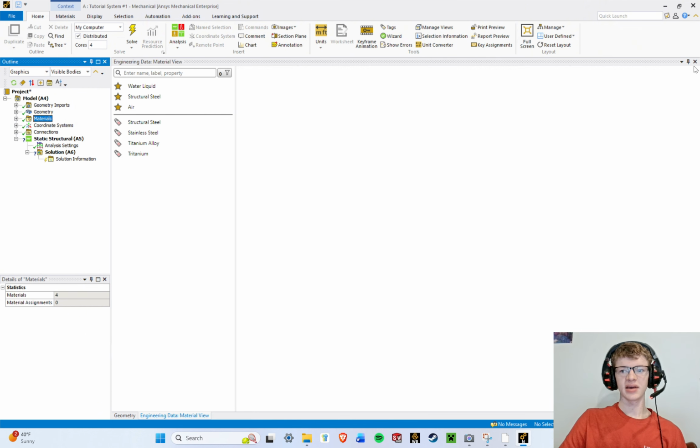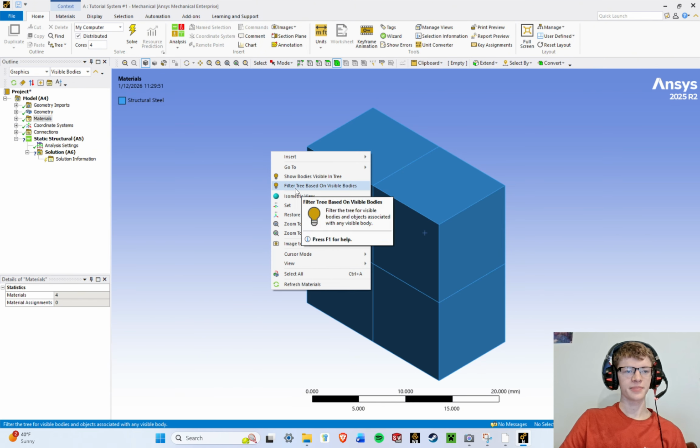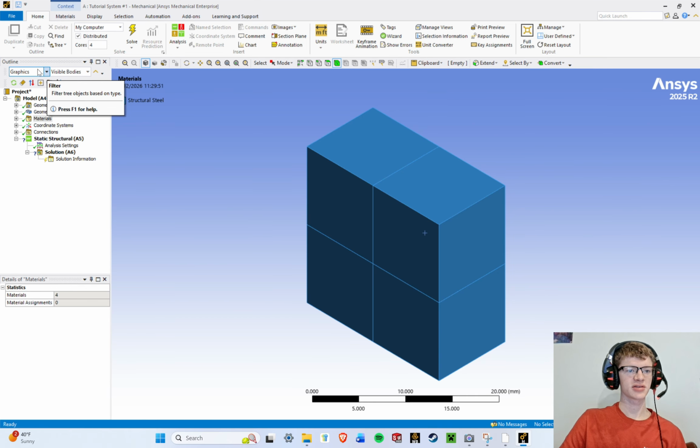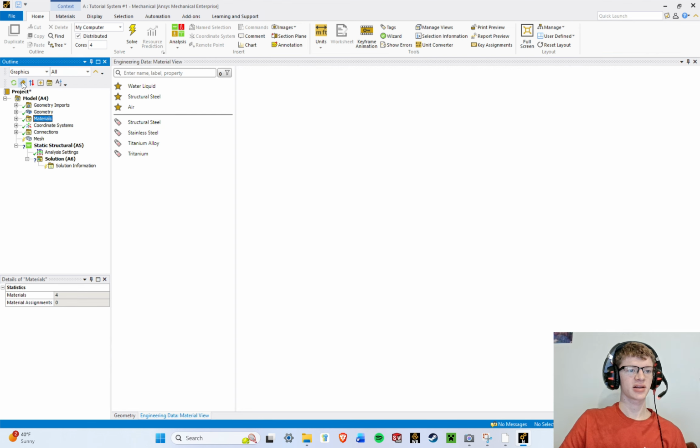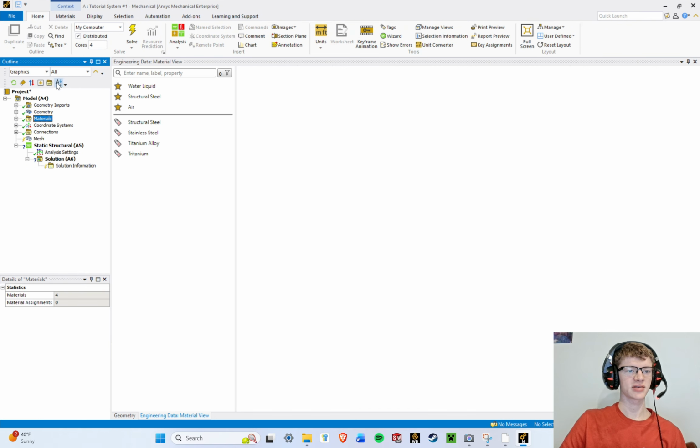If you click it, then this is going to pull up and you can see there are going to be a few items removed from the tree, and sometimes you'll be looking for something in the tree and you'll open it and you'll see it's just not there. Where did it go? It can't possibly have disappeared. And that's because when you click this button, it's going to add some things to the search engine here, and that is going to remove items from the tree, and that's weird. So just click clear search and that will put everything back in the tree. Beware, sometimes if things are missing from the tree, this can be why, and this button right here is going to be your friend.